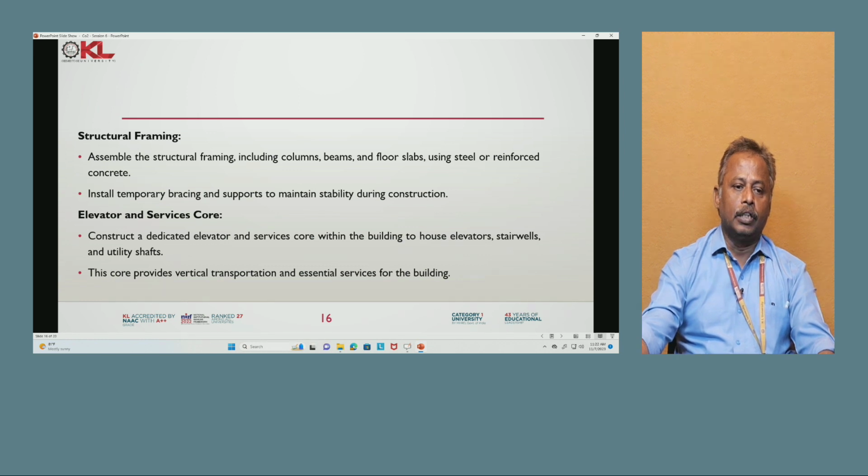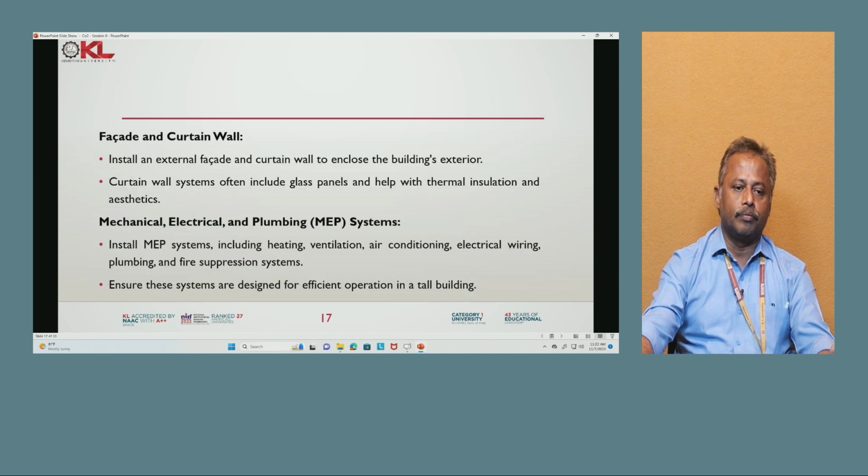Next is structural framing. Assemble the structural framing, including columns, beams and floor slabs, using steel or reinforced concrete. Install temporary bracing and supports to maintain stability during construction. Next, elevator and service core. Construct a dedicated elevator and service core within the building to house elevators, stairwells and utility shafts. This core provides the vertical transportation and essential services of the building.